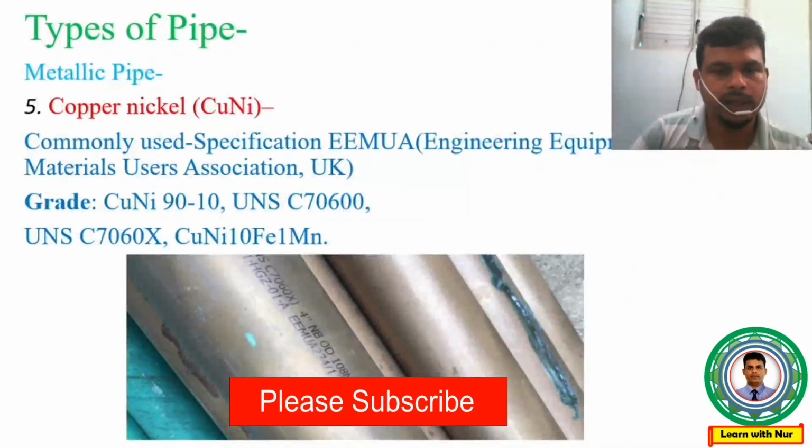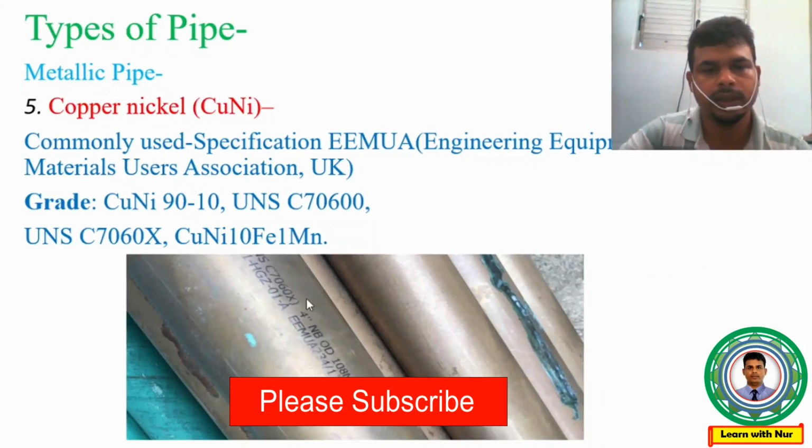Then we see these pipe photos. You can see the writing C7060X. This is actually for the copper nickel identification. So you can check here and identify this is a copper nickel pipe, and you can see the specification EEMUA. So when you see these things, you will be able to understand this is a copper nickel pipe.